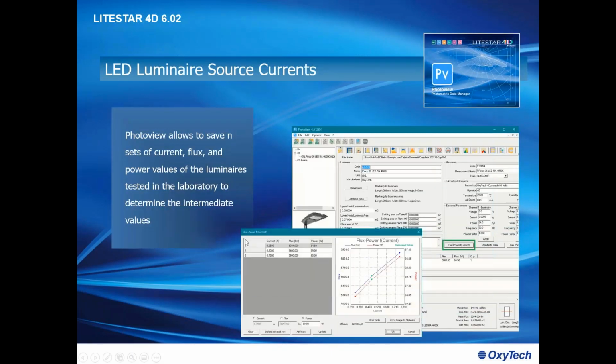Next one, LED luminaire source currents. One of the main issues now characterizing the manufacturers and the people working on design in the market is the management of the driving currents of the LED products, which is now forcing the manufacturers to produce one IES file, one ULUM.dat file per any different current setting.